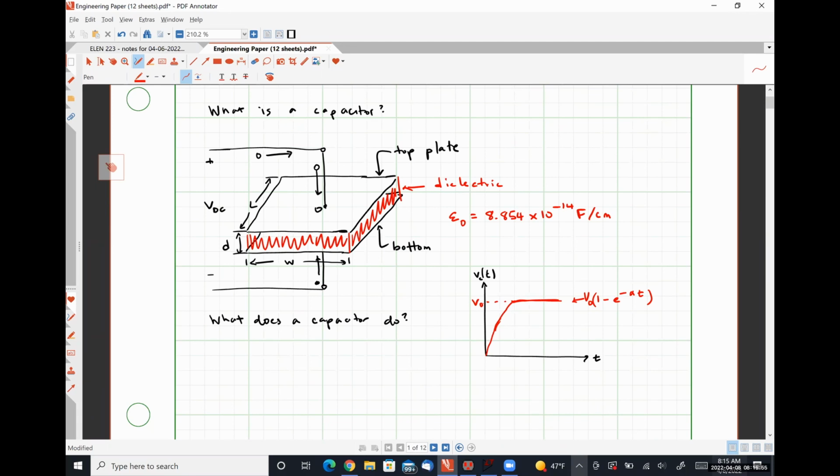Right, it doesn't allow electrons to flow. So how do we get current to flow in a capacitor when there are two plates that are physically separated, meaning that there is no contact or no path for current to flow through? Well, it's all about moving charge on and off the plate. It's going to take some amount of positive current to push charge onto the plates. If we let the charge move off of the plate, that constitutes a negative current because the charge carriers are moving in the opposite direction.